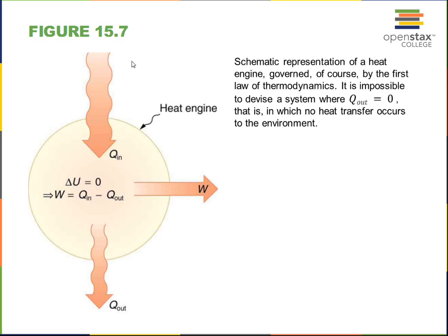For heat engines, we burn wood, we burn coal, we burn oil, we capture the energy from radioactive decay, whatever the means is, but we create some high temperature reservoir up here. And then Q sub H, that's the energy that's leaving the high temperature reservoir. And I'll often refer to Q sub H here. And Q sub C, that would be the energy going into the cold reservoir. But the names here are fine.